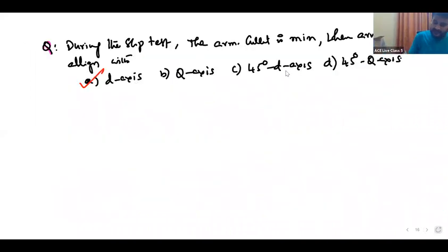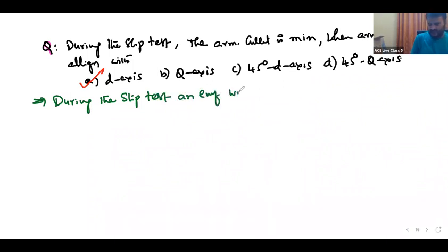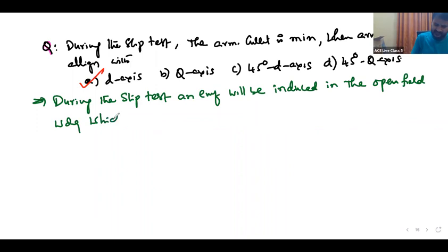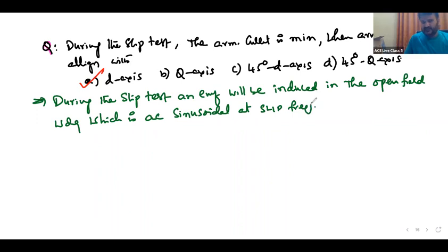I am writing the statement. During the slip test, an EMF will be induced in the open field winding, which is AC sinusoidal at slip frequency.